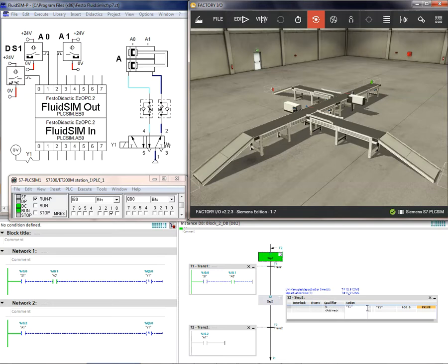Y1 connects when diffuse sensor 1 and A0 turn on, Y turns on, and then when A1 turns on, at the end of this cylinder, this condition is passed and it goes to step 1 as S1, as you can see in transition T2.